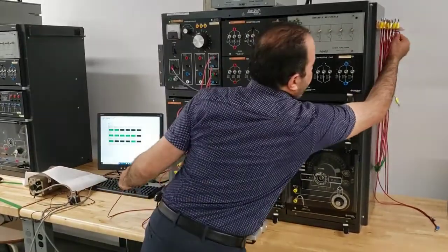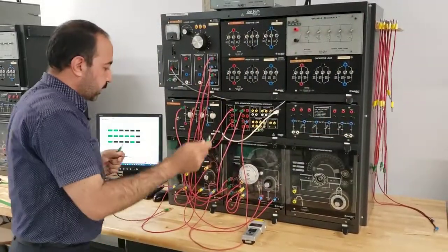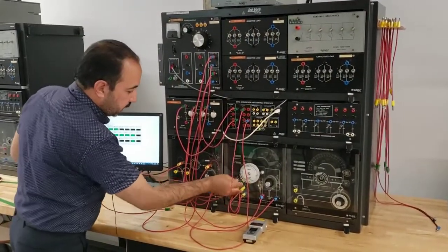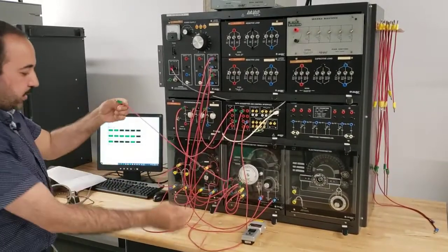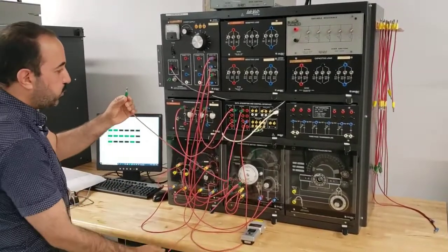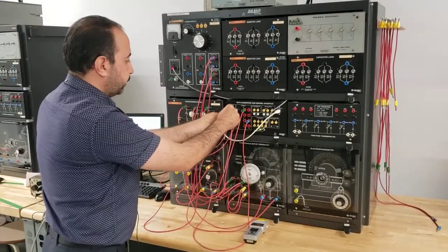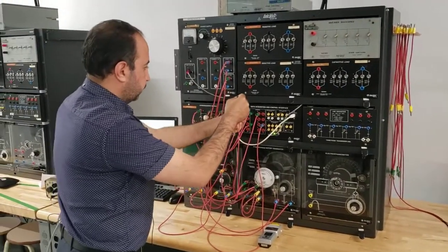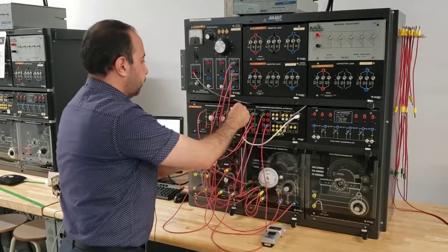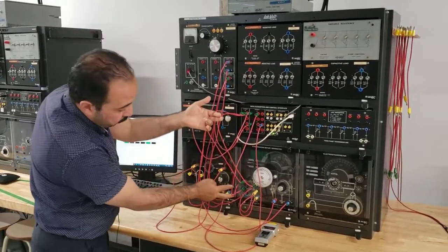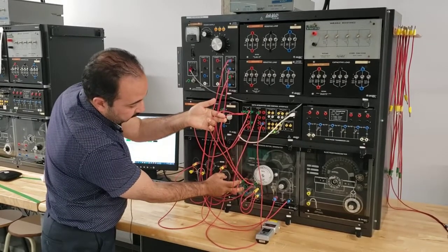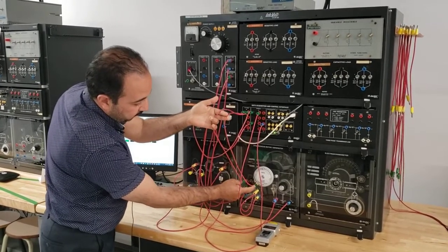And I would like to measure the voltage as well. So I will bring another wire for measuring the voltage. So I would like to measure the phase voltage. So I will connect this to this. These two are measuring the phase voltage. I will connect them to E1. If you would like to measure line-to-line voltage, you will connect your voltmeter between these 2 points. But here I'm connecting my voltmeter between these 2 points.